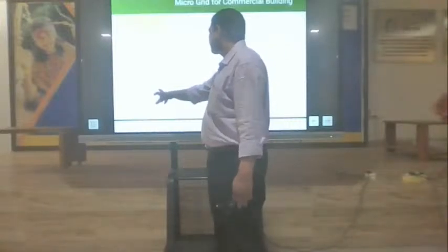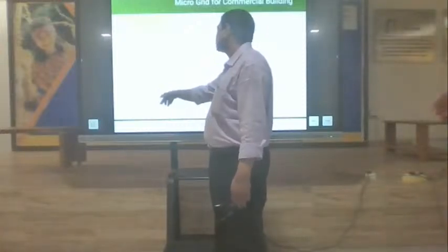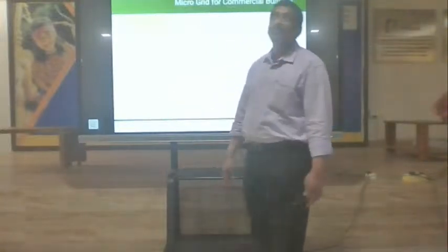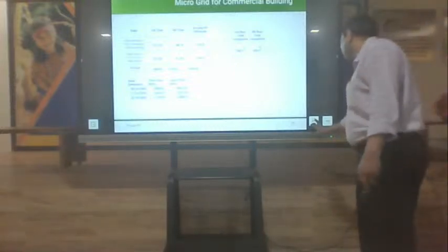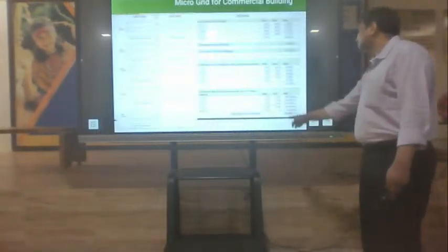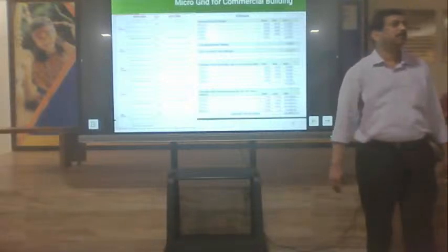So overall for the day, this is the total solar generation. Per day, we were able to generate per floor 8 units and 8 units, 16 units. We had 4 floors, so 4 times 16 is 64. What was it supposed to generate? It was supposed to generate 146. How much have we generated? 64. So we didn't even generate 50% of the estimate.